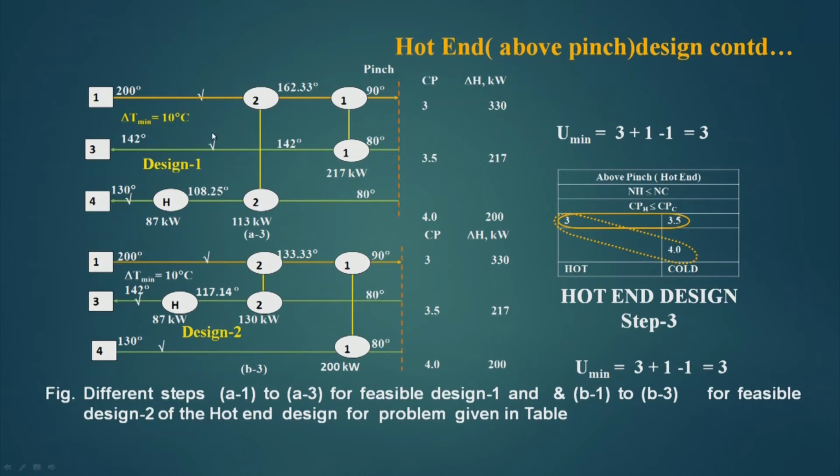So, now all the 3 streams are ticked off for the design 1. Once the streams are ticked off, it means that the hot end design using the pinch rule for the heat exchanger network is complete. So, hot end is complete for design 1.